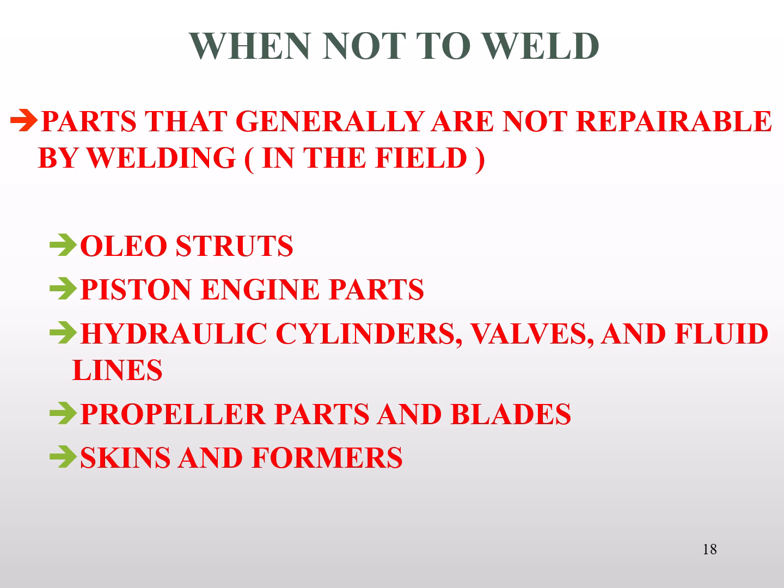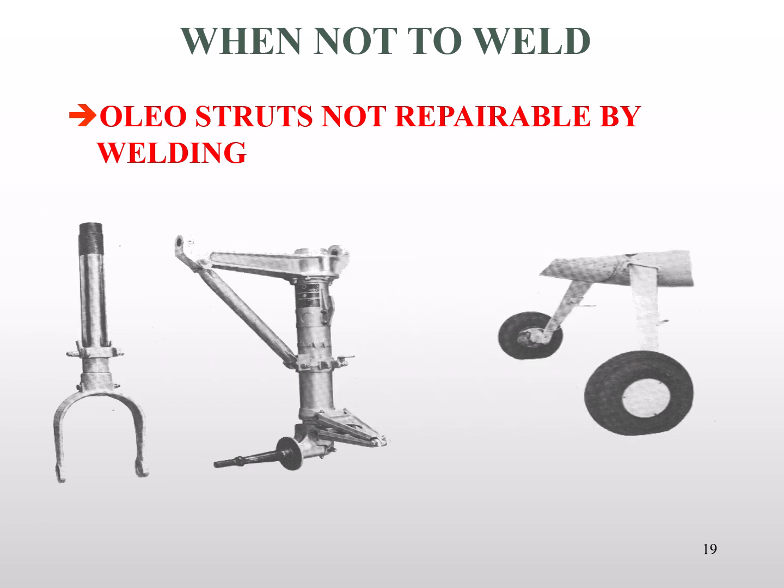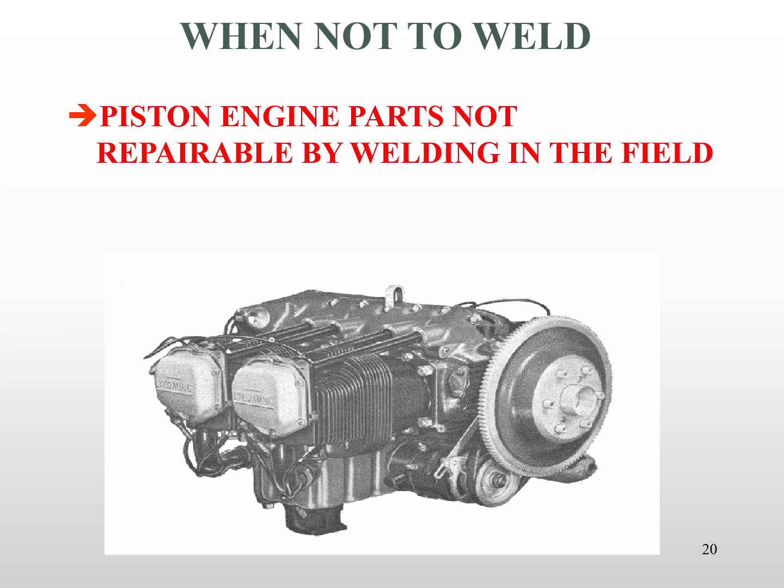So, a good list of things not to weld. In a couple of pictures, this is simply the things on the previous list. You can see them and sort of identify with them. No internal engine part, or external part for that matter, is eligible for a welded repair in the field. At times, engine parts are welded as a part of a remanufacturing process, but that can only be done at FAA approved repair stations in which they have the authority and they've been inspected and proven their ability to do the thing.